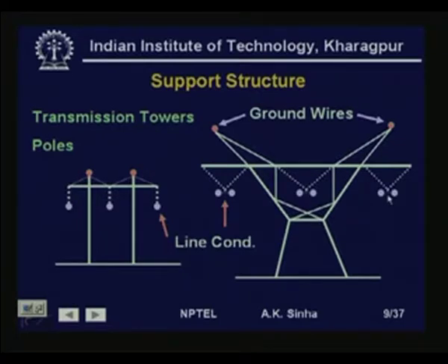The reason behind this is that it increases the effective radius of the conductor, therefore it reduces the electrical stress and so the corona losses, and this also reduces the inductance, which is very useful in terms of reducing the voltage drop.